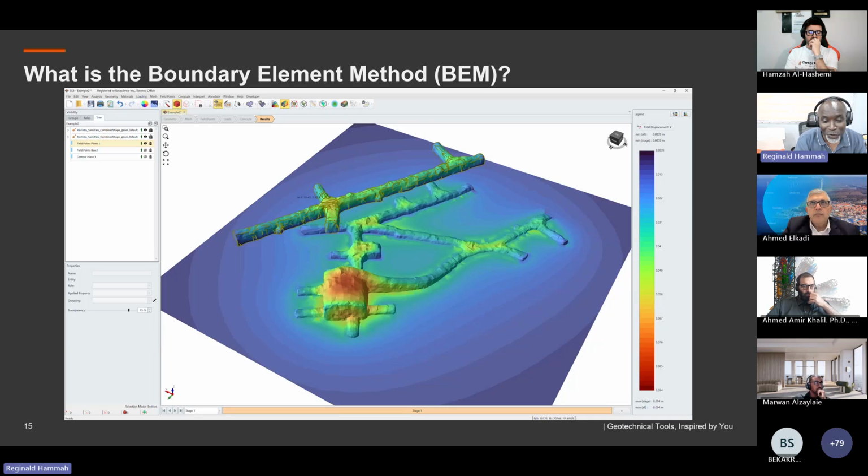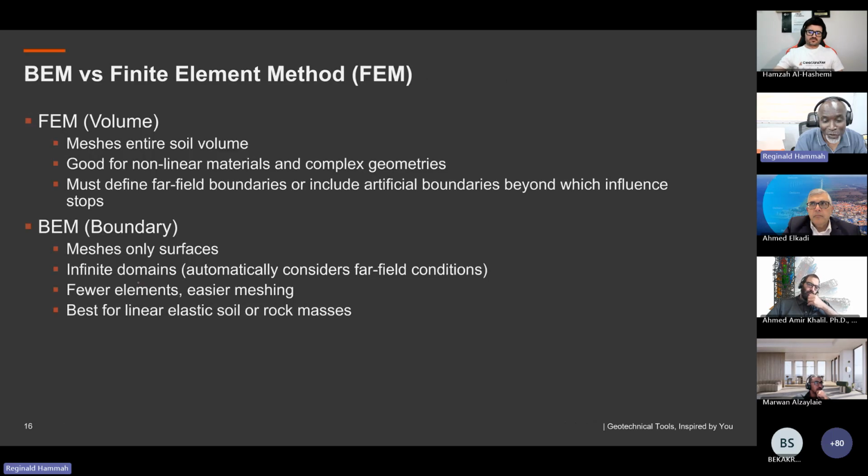Originally, we solve for stresses and displacements around the excavations. Once we have that, if we were, for example, to specify this plane, and it's actually divided into grid points, and we interpolate, now we can find what is happening on the plane. So this is how the boundary element works.